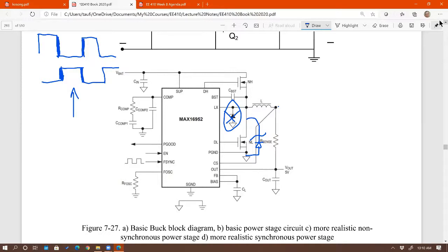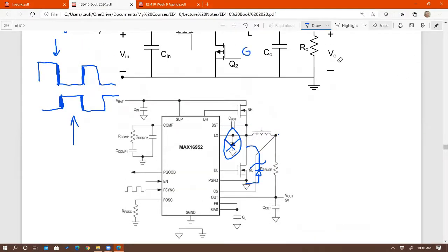The reason being what? Anybody? Let's see if we can analyze the circuit. Why do we need the Schottky? Is it for protection during the dead time, where the inductor has to still be able to have current go through it, or it's going to cause a voltage spike? Very good. Awesome. That's the answer. Remember this dead time right there?